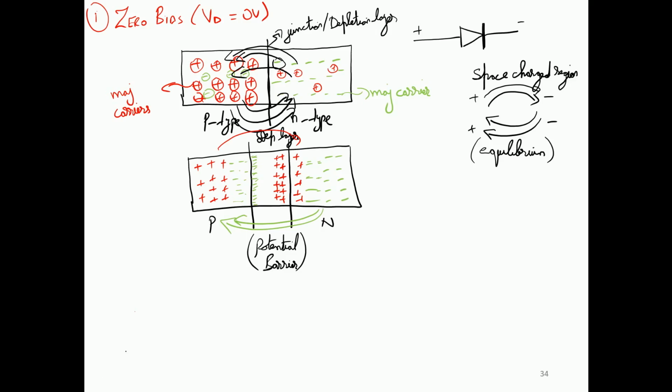How? Because we also know that electric field, as per the equation E = V/d, or we can say that voltage and electric field are related mathematically as such. So the voltage or a potential barrier is created because now the electric field is moving in the opposite direction, from the positive side towards the negative side. Thus in the depletion layer, this is how a potential barrier gets created, because the positive